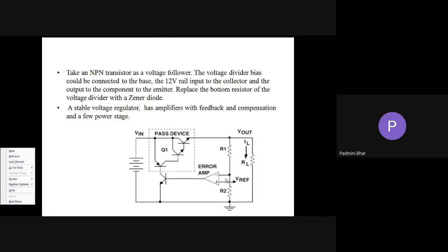So it discards the difference, and 5 volt is sent here. Then again one more sample of the input. So at regular time intervals, samples are taken and compared, the difference is discarded, and then the constant value is given out to the transistor. In this way it works.